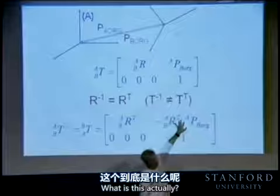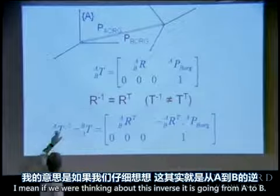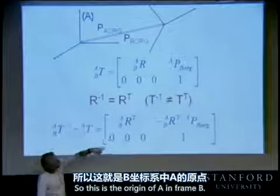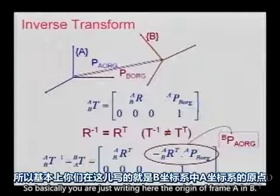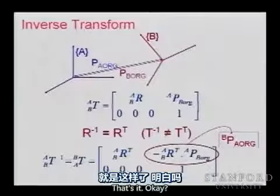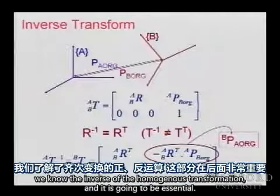What is this actually? If we were thinking about this inverse, it is going from A to B. So this is the origin of A in frame B. So basically you are just writing here the origin of frame A in B. That's it. Okay? So now we know the forward, we know the inverse of the homogeneous transformation, and it is going to be essential.